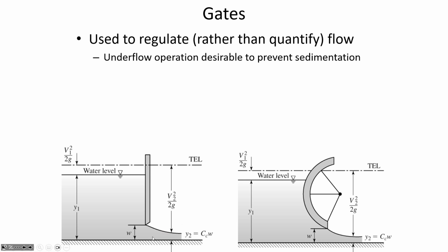So this is supercritical flow in a lot of cases. And if we have a mild slope, then flow under the gate is one of the main ways that a hydraulic jump can form downstream, because you've got supercritical flow where it shouldn't necessarily exist, which is to say on a mild slope.